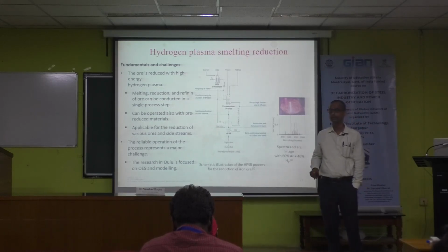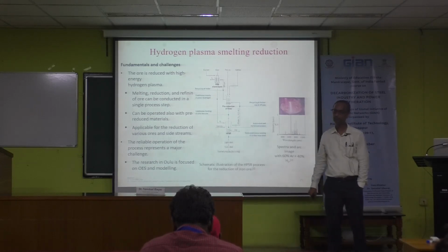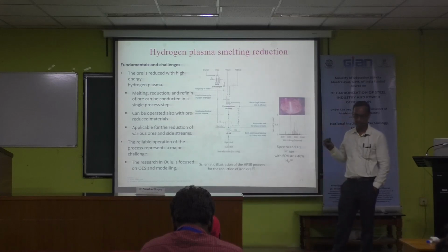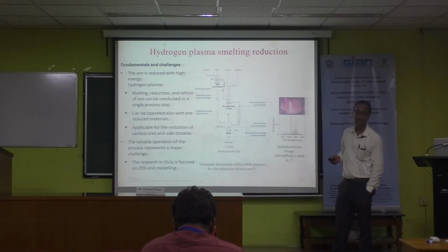Therefore, our project in CSIR Australia is how to treat high gangue containing Australian ore and Indian ore in plasma smelting. It is very difficult. The free board area requirement is high. Another is the conductivity of the arc. Otherwise, the arc will be disconnected. If your requirement is a constant arcing, a stable arc, maintaining the stable arc is very difficult.